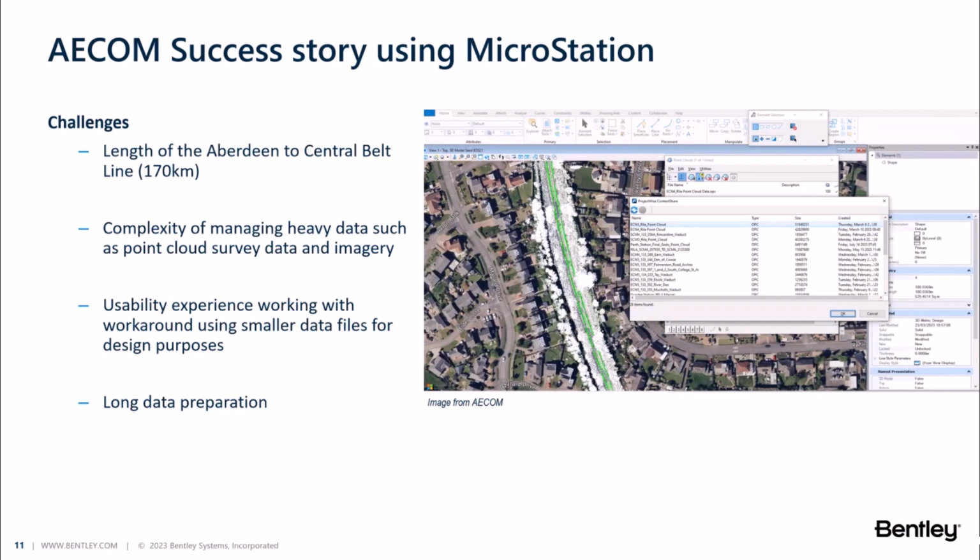But now with the advent of iTwin Capture and iTwin services, it's kind of revolutionized how we use that data a little bit. For example, once upon a time we would have had to take a large point cloud and cut it up into, say, 5 to 10 gigabyte chunks to be able to import it into the authoring software, typically MicroStation.